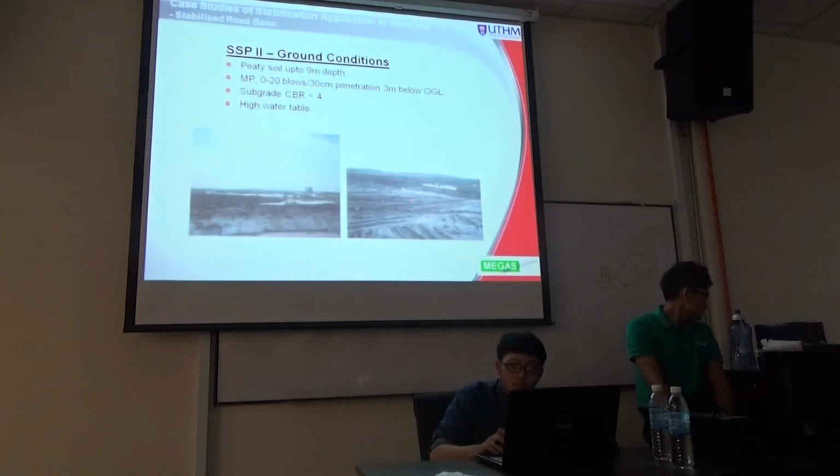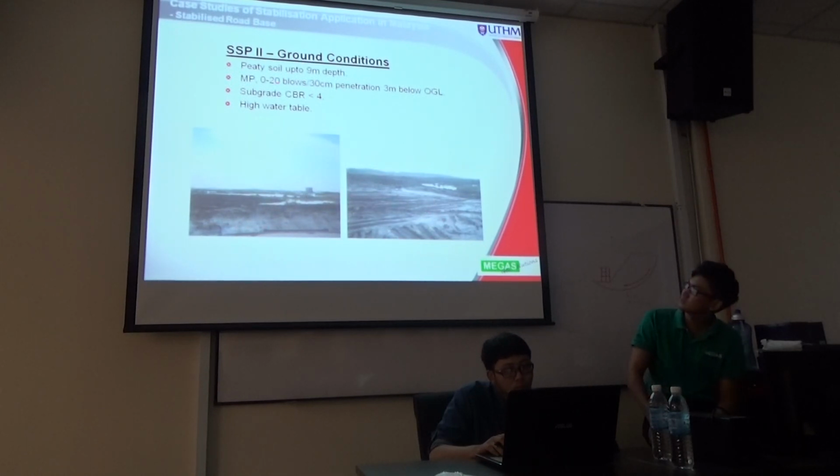Okay, so this is a very virgin view of the site after the site clearing. You can see a mix of the peat soil, some with a low CBR, less than 4, and a very high water table. It is wet everywhere.